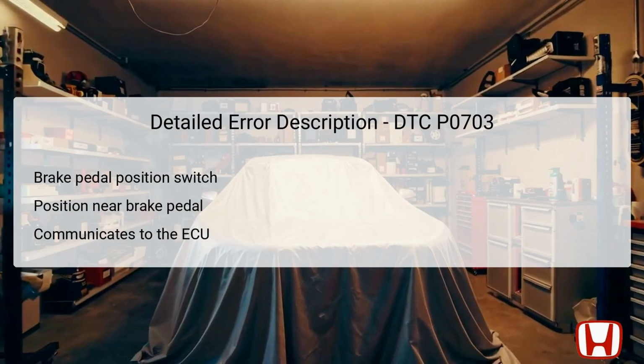Located near the brake pedal assembly, this switch functions as a normally closed contact, indicating when the brake pedal is not pressed. It is essential for various safety features, notably in controlling cruise functions and ensuring the proper idle when braking. If this switch fails, it can generate incorrect signals, leading to unintended vehicle behavior.